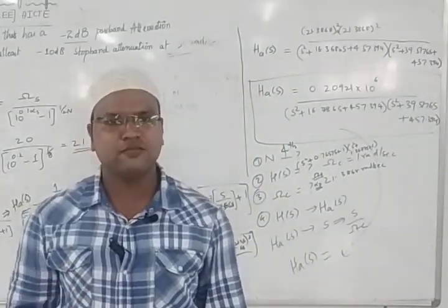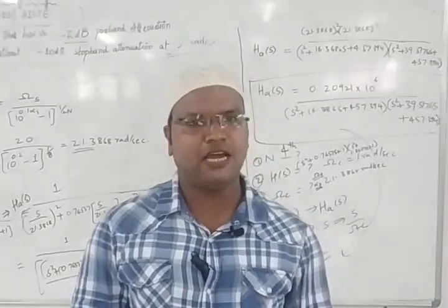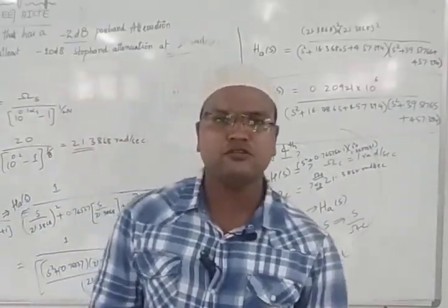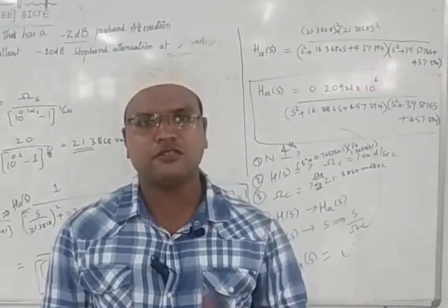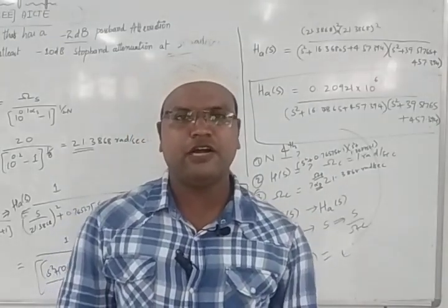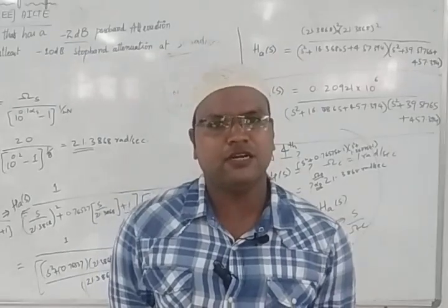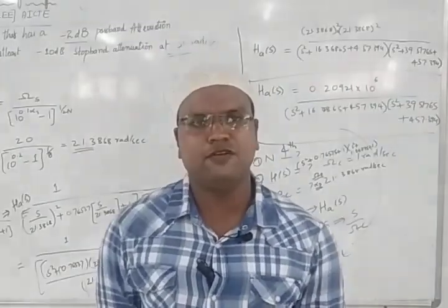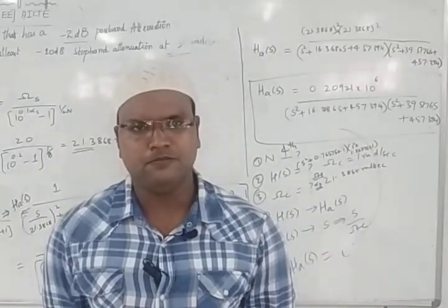Okay, so in the next class we will see the Chebyshev approximation design. It also has the same order formula, but instead of log, we will use cosh inverse x. We will take the inverse hyperbolic function, and we will find the order, transfer function, critical frequency, then poles and zeros, and then by putting in the critical frequency we will get the transfer function.